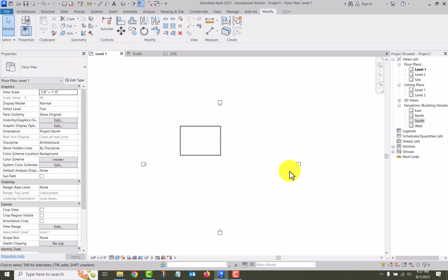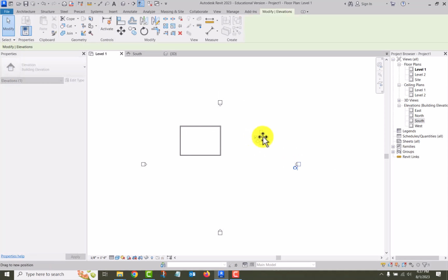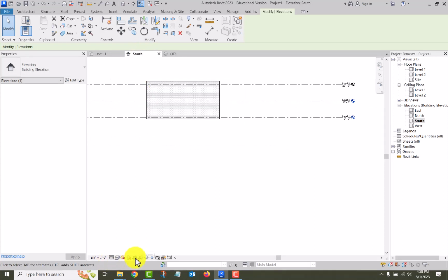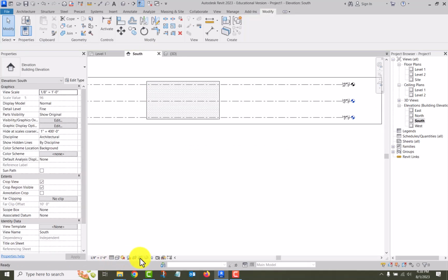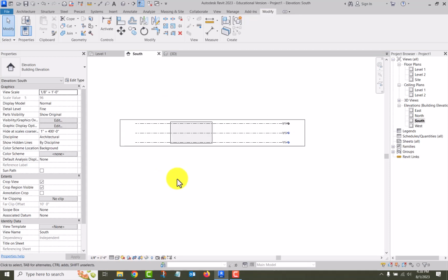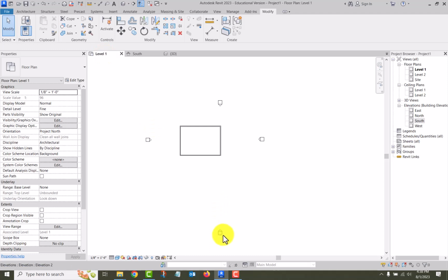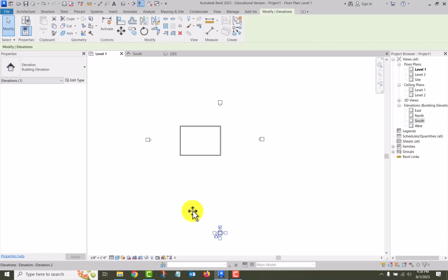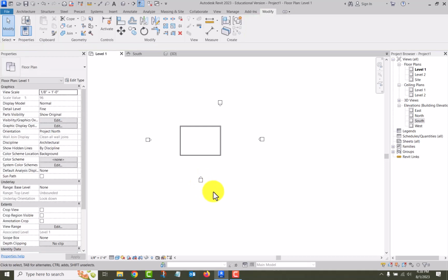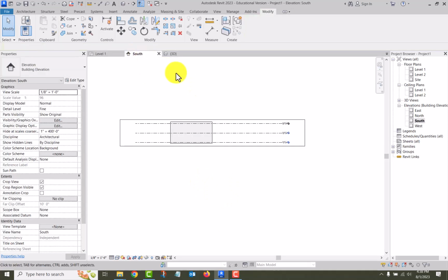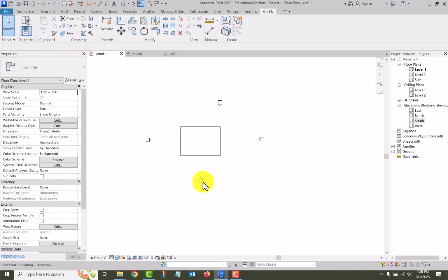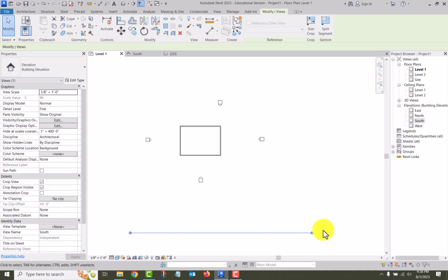And if you've drawn this thing and your elevation markers need to be moved, maybe they're inside or maybe they're outside, you can just grab the marker, click it and move it. Okay, and all that does is change it. Let's look at this. Let's go to show crop region. So you can see the crop region there is kind of big and we're off centered. So if I come back, well, the crop region didn't change, just the marker changed. There's my crop region there.